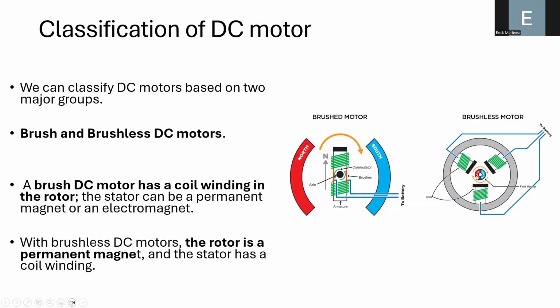And we need to perform an electronic switching of the solenoids by using transistors. Also, based on a DC voltage, we are generating an AC voltage through the electronics. It's very similar, for example, to the process that an inverter in an electric vehicle does, because it converts the DC electrical energy into AC electrical energy. And we are doing a very similar process by generating this magnetic field that is producing the stator, that is basically moving around the rotor, okay?